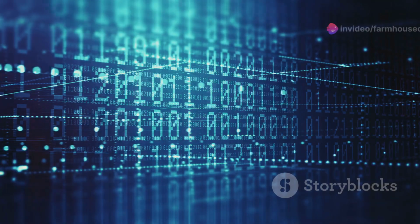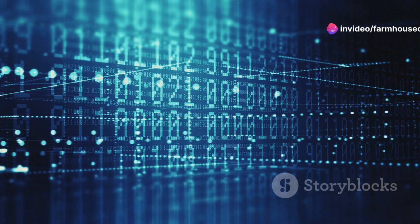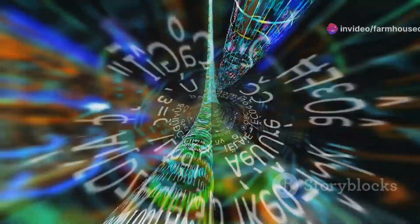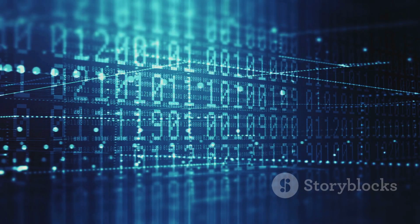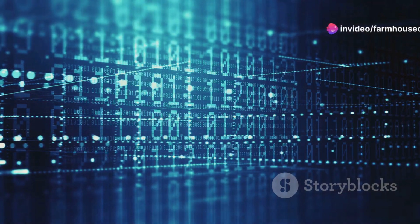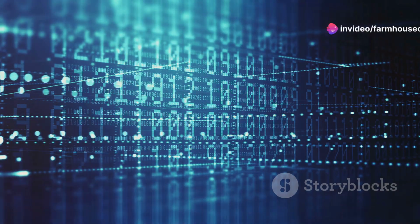While decimal is intuitive for humans, it is not as directly compatible with digital circuits as binary. Converting between decimal and binary is a fundamental task in digital logic design. This conversion process involves dividing the decimal number by 2 repeatedly and recording the remainders, which form the binary representation.